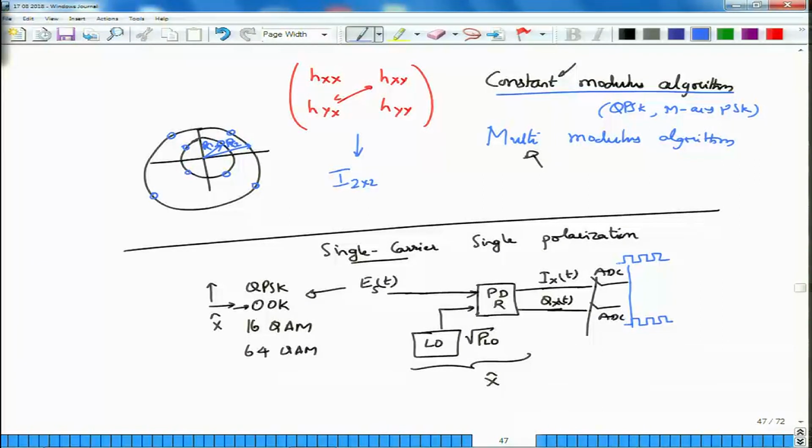So, this minute difference that you are seeing here is called skew of the clock, and therefore, you need to de-skew the clock. De-skew means they are not aligned with respect to each other, so you just have to make them align. The timing of these two should essentially be the same. So, the skew in the clock has to be recovered.